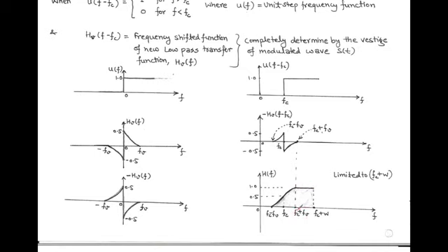And accordingly, the negative peak of the odd symmetry meets the positive peak and varies continuously. And from the designing point of view, the transfer function of the sideband shaping filter must be limited to fc plus W. Here W is the bandwidth of the message signal. So in this way we get a specially designed sideband shaping filter for the generation of vestigial sideband.